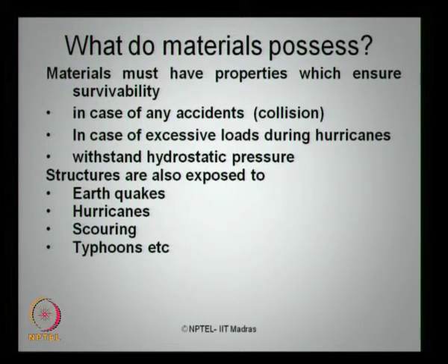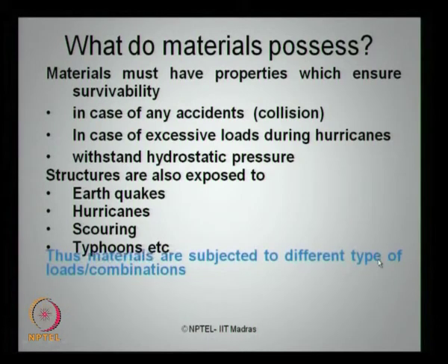Now look at an offshore structural system under the present environmental loading. There is a very serious combination of different kinds of force systems, different combinations of these forces acting on the members, different effects caused by the environmental nature on the member material, and the material also has specific physical and structural characteristics. Now the algorithm of selection of material for an offshore structural system is growing complex in nature, and therefore we must clearly understand a guideline on how to select this material for ocean applications.